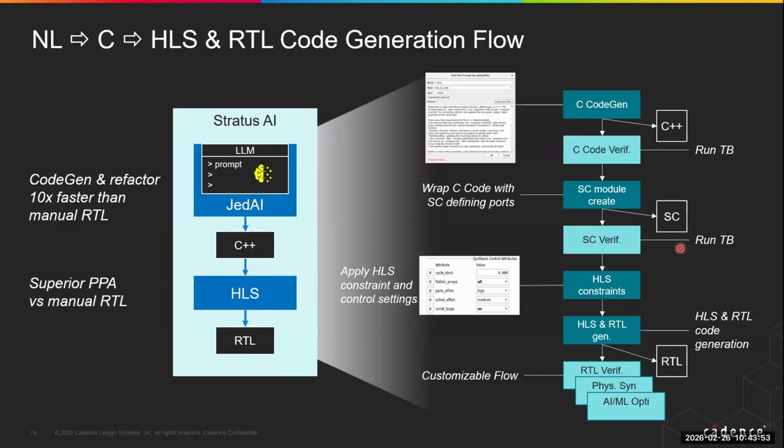And then, similar to these steps that preceded, verification is also a key piece of what happens after you produce the RTL as well. Now, if you do this correctly, then you can have one test bench that's used against all of these different abstraction versions of your design.